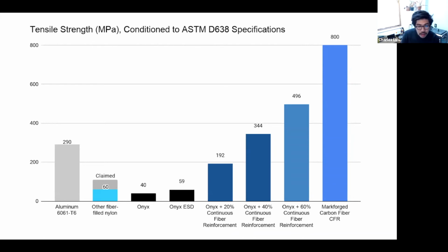So how did you achieve 800 megapascals? That is based on a pure printed beam. If we're talking about ASTM standard beams, we printed a pure fiber beam and measured based off of that. Practically speaking, you'll never achieve that 800 megapascals with a printed part unless you were making a beam. But you could see somewhere close here, like you see 60%, you can get 500 megapascals.